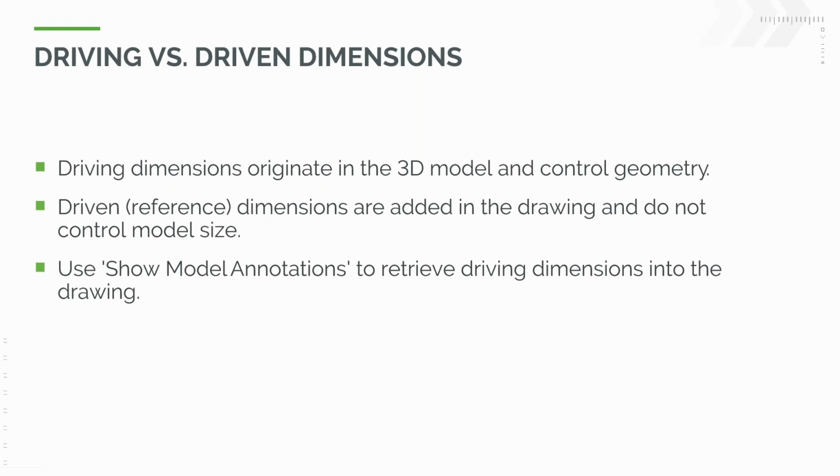Driving versus driven dimensions, okay? So driving dimensions are controlling dimensions, okay? So they come from the 3D model. They're used to define all of our features for extrudes, revolves, etc. Okay?